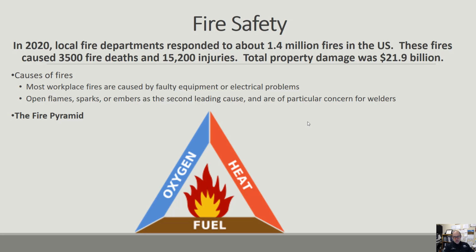There was a local case a few years ago that a nightclub venue was burned not to the ground, but was seriously damaged by a fire, and there were HVAC technicians working on the ductwork, and they were cutting the ductwork open with grinders, and the sparks got inside the ductwork and lit a bunch of basically dust bunnies and stuff on fire, and the fire got away from them and did quite a bit of damage to the building. As welders, we're always throwing sparks around, so we need to be really cognizant of all the stuff in the area around us that we could possibly set on fire, and try to keep the area as clean as possible to keep that from happening.